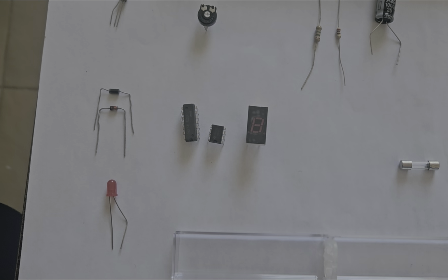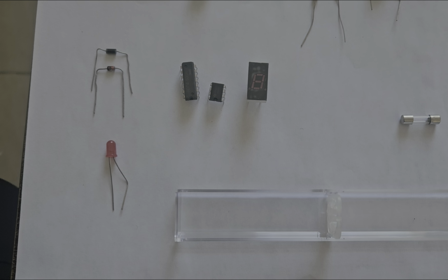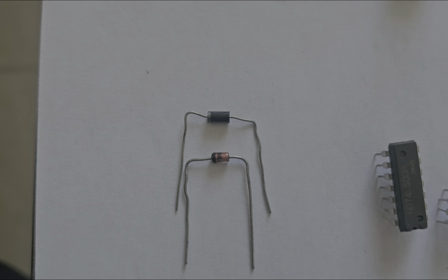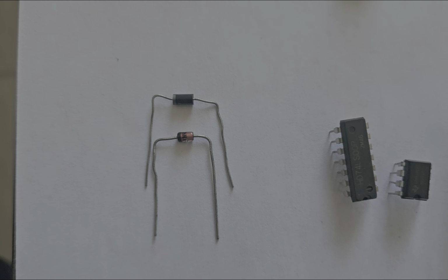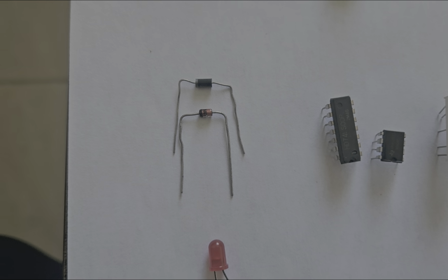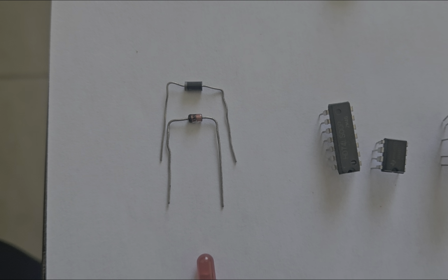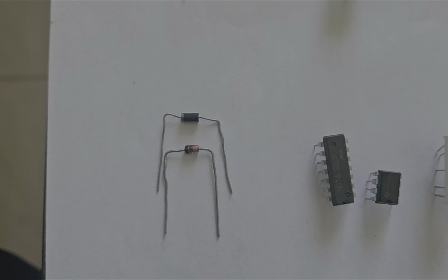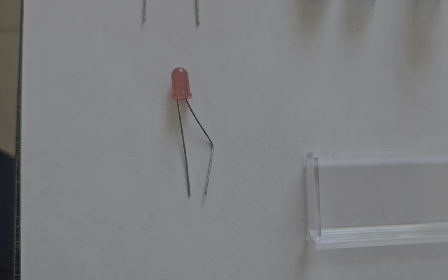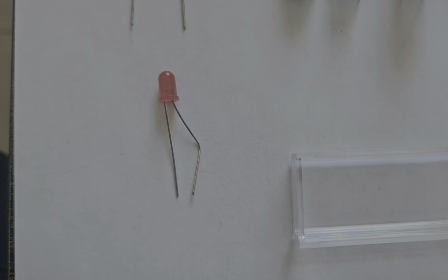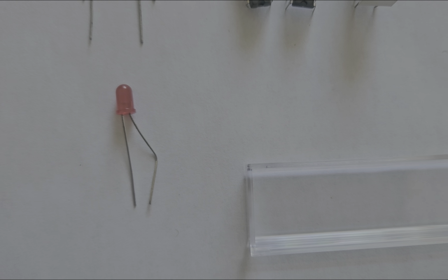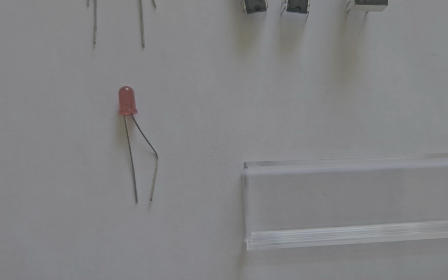And then the other 2 or 3 components that I would like to take you through. As we've spoken about a diode, you also get another type of diode called a Zener diode. This one is used for voltage regulation. It also allows current to flow in one direction, but it also has limits in terms of what voltage it allows to pass. That's why it's used for voltage regulation. Then at the bottom, it's a light emitting diode. It's an LED. It will emit light when current flows through it in the specific direction, and it won't allow light to emit when it is reverse biased.